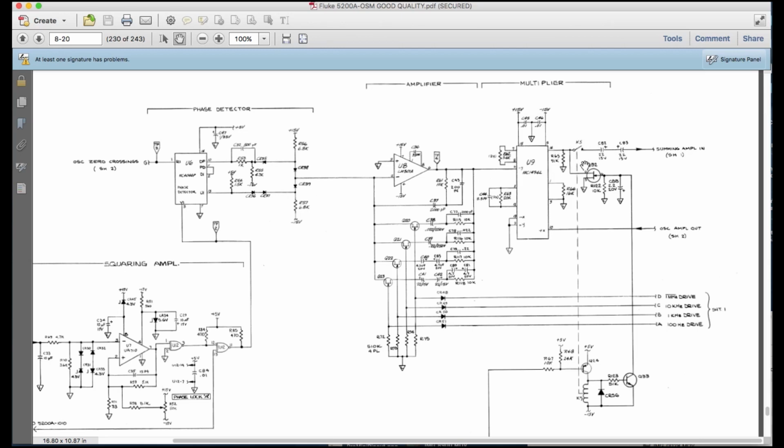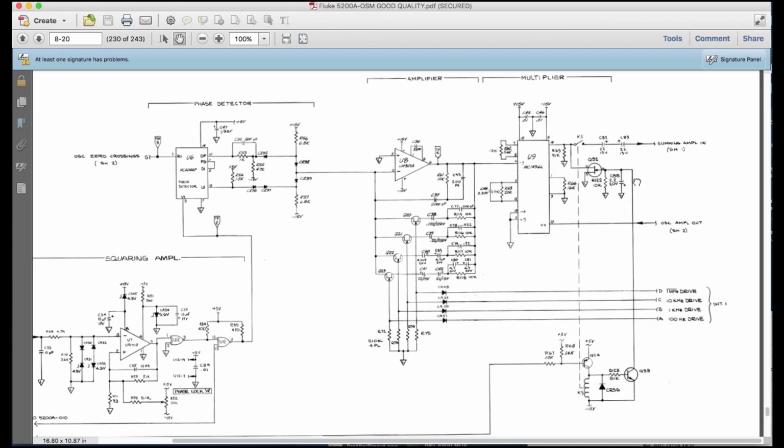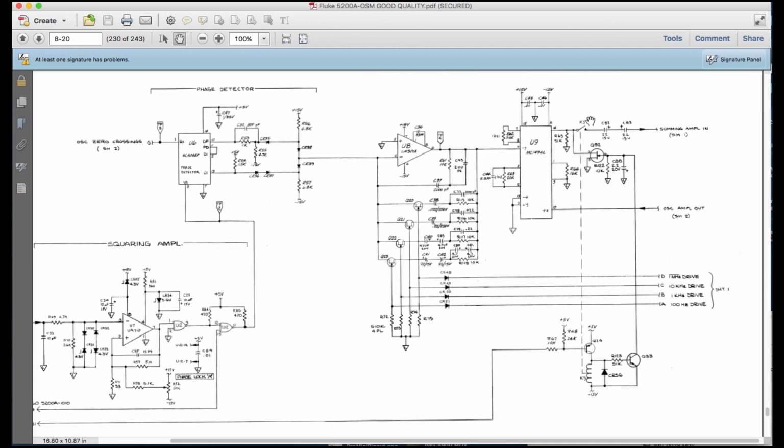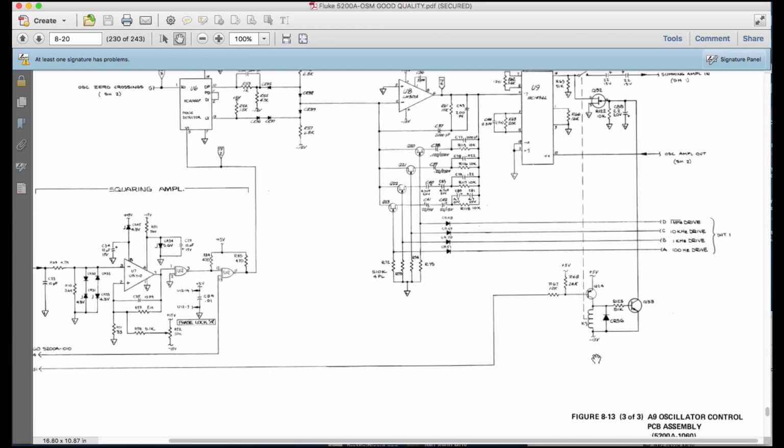And then it goes through this bit here, which is a little bit interesting, because you've got a relay here, K5, which is driven from down here, which then passes through the summing amplifier input. So that is what drives the oscillator frequency, the input frequency, right? So this is doing that pulses, which is what's driving the oscillator. So this is obviously switched in and out of circuit depending on whether it's being used or not. So the relay is controlled by K5 relay here, there it is.